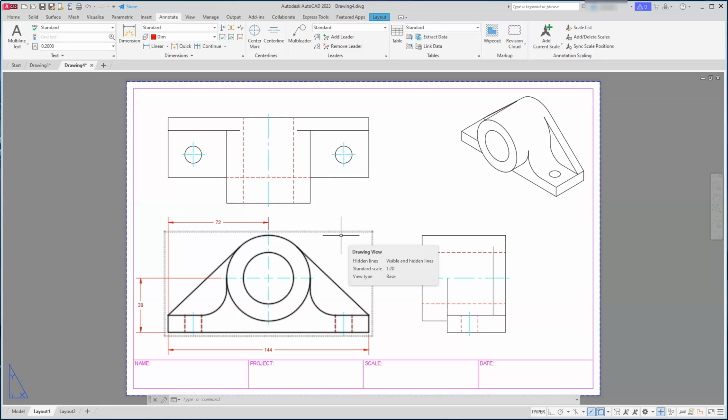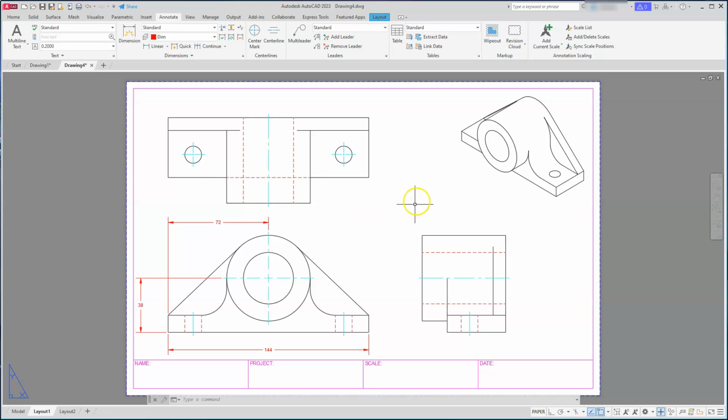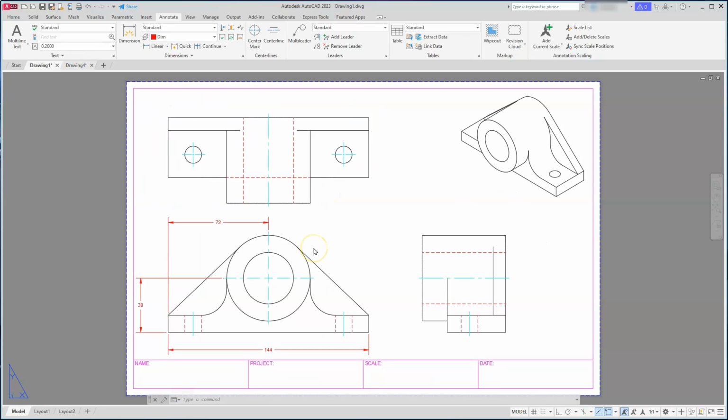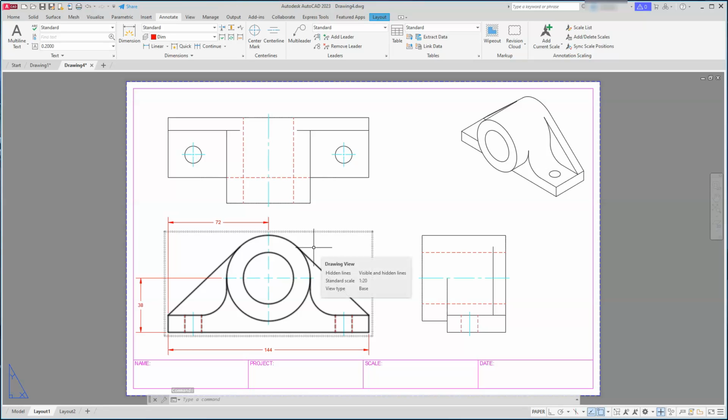So this kind of concludes everything that I need to show you on this video. And once again, you can put more or all of your dimensions on this one. And you can see how extremely fast it is. If you create the model, the views are nothing to create. And you can see that we missed a couple of hidden lines, especially this one, on our previous drawing. So if I go back and I switch here, you can see there's a hidden line that goes right across there that shows that edge underneath the bottom. So it's extremely quick if you know how to do the modeling. And you can see if you can kind of break the model up into individual pieces, it'll make it that much simpler.